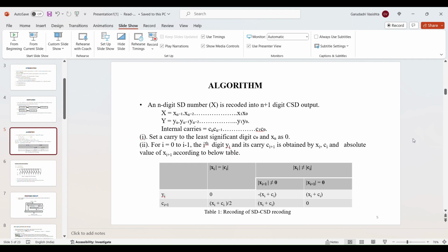So we can compare this circuit with a ripple carry adder, which will calculate its previous carry before calculating the next carry. So for calculating the final output, we need to calculate all the carries beforehand. So as Pavan said, it will take order of n time complexity.